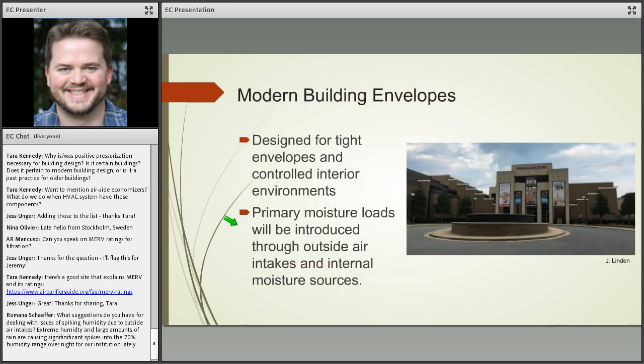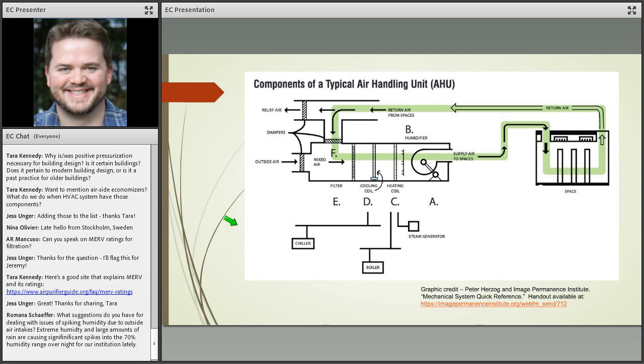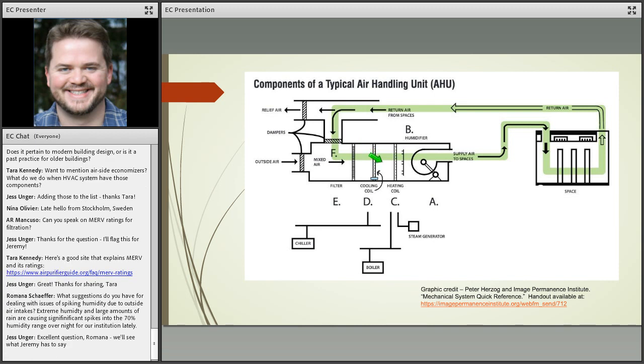And what I'm actually going to do here is just walk through that. Bear with me for one moment. On this diagram here, we were talking about where the air comes in, the mixed air condition with a warm temperature, high dew point condition. We take it across the cooling coil here. That drops the moisture out as we subcool. In this space between the cooling coil and the heating coil, between here and here, this is where the air comes off the cooling coil at a very cool temperature, a very high relative humidity, oftentimes 100% RH. We then reheat that air, we bring the temperature up, we bring the relative humidity down, and that creates the safe condition to then supply out to the space.